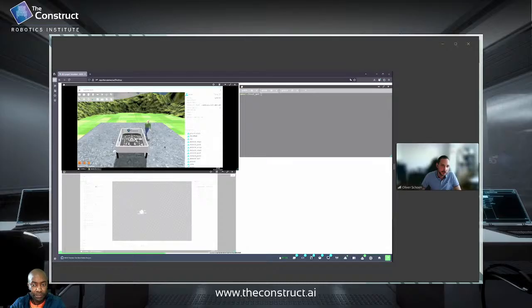And now, if I can show you, we can also visualize our LiDAR scanner in the Gazebo simulator. So, just add this part here, and then we need to quickly change the topic, and then it will also show the scanner. It should, yes. And what you can see is that some of the rays are being blocked by the different objects, which basically means that it's working perfectly fine, because this is what you want to have. So the LiDAR scanner and the objects are working fine. It's kind of like the signs are at the same height as the robot scanner, so that's why it's hitting the signs and not the small bars, so to say.